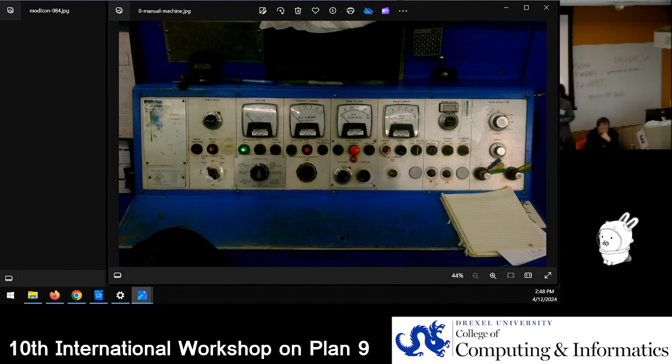Right over here, you would have to manually cycle through your vacuum. Somebody would have to sit there, look at the vacuum gauge, and know when the appropriate time is and know the pressures. So the person had to automate the process, and they had to be educated about the process. An operator not only had to know how to weld, they had to know how the entire machine worked. In this very manual process, you would have your motor control for moving the table around, you would have your vacuum, then you would set your beam current parameters and your high voltage power supply,